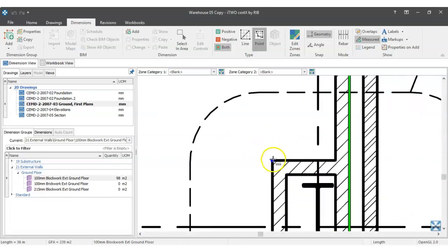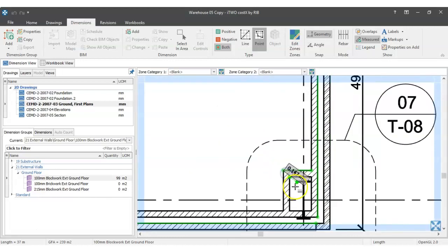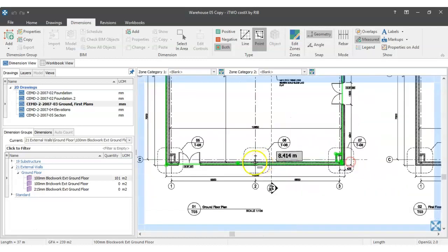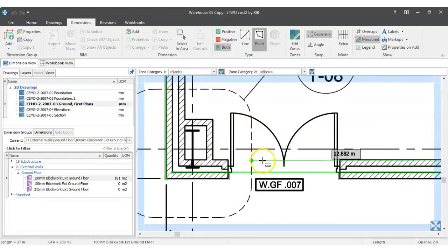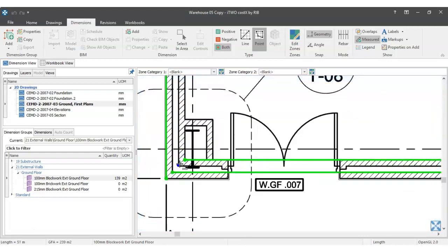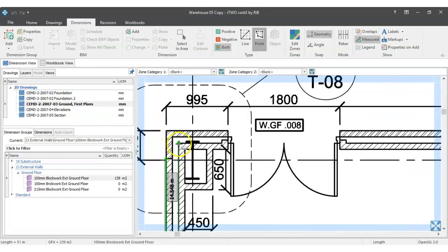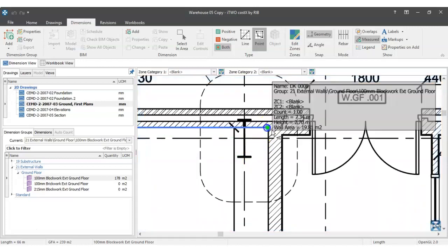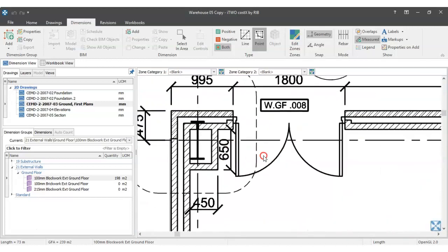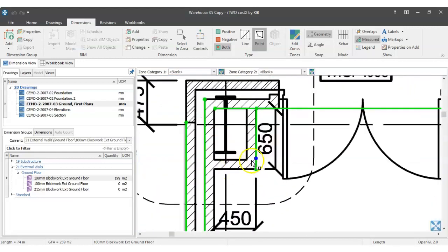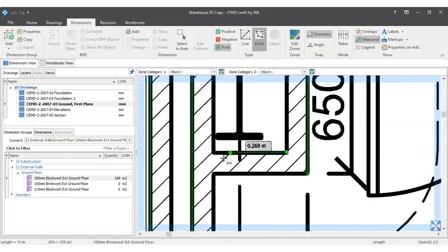And measuring the corners, I'm going to go from outside to inside, so that covers me there. I didn't measure this wall, so maybe starting on the inside here rather than the outside. This is the internal leaf, and there we go. And then going from the outside here up all the way to right there, and from here to here, because this is where the 215 begins, and then make sure I've got my corners measured here, right there to there, and then because I don't want to double measure this corner, I'm going to click from there to there.